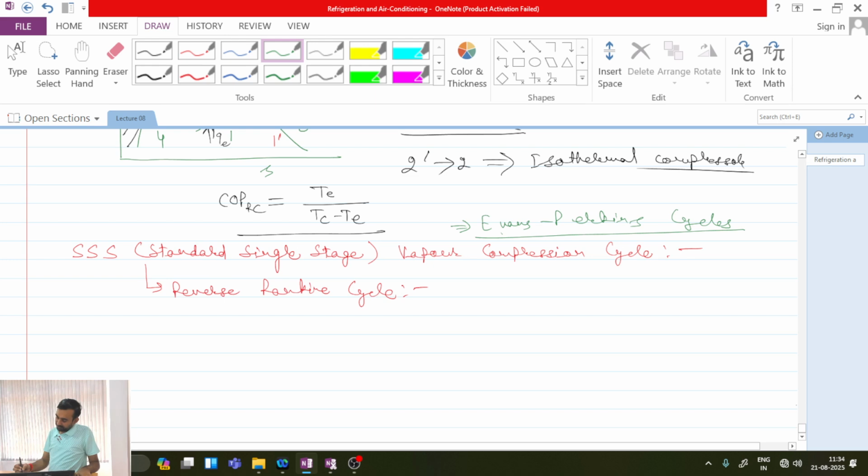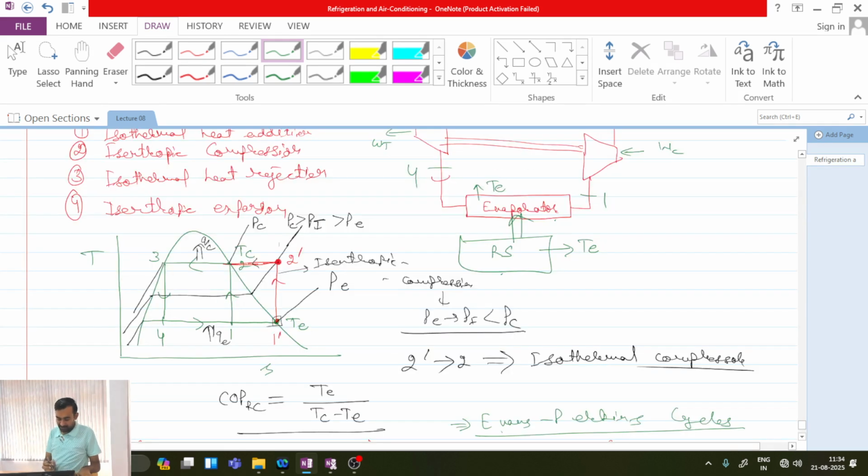Now in the previous cycle we found that the 2-2 process is actually creating the trouble. So my problem will be solved if I make two assumptions here. First, in place of assuming totally reversible processes, let me assume that all the processes are only internally reversible. If processes are internally reversible, then the processes are possible. Why? Because internally reversible means within the working fluid there should not be any temperature gradient. And how is that possible?